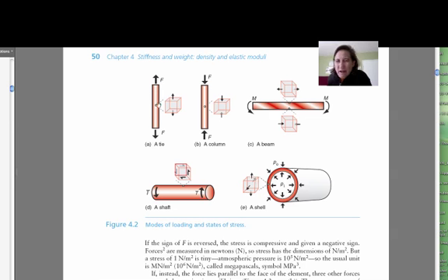And if you were to look at a tiny little piece of material, somehow magnify a little section of that material, that's what this little box is showing here. What it would look like is essentially a uniaxial set of tensile forces on this little box, or compressive forces on the box. Now, if you're actually bending something like a beam, on the top you'd see tension, on the bottom you'd see compression. If you had a shaft where you were trying to torque the shaft, you'd see inside this that a little element would actually be under what's called a shear stress state.